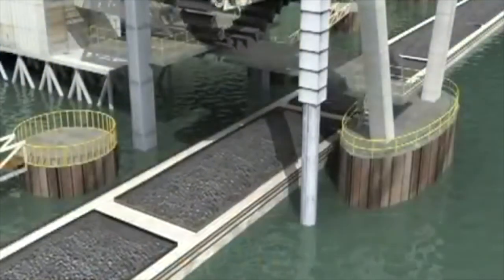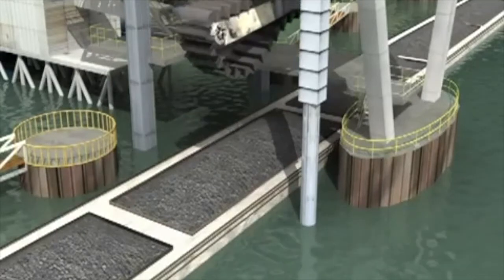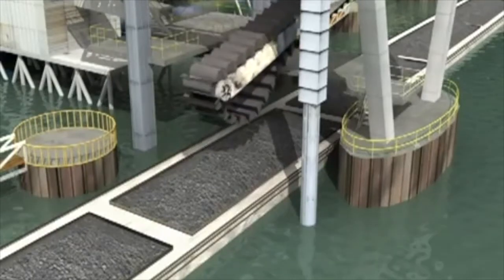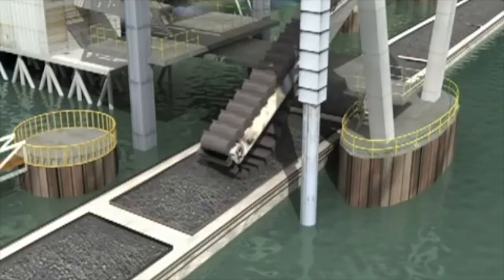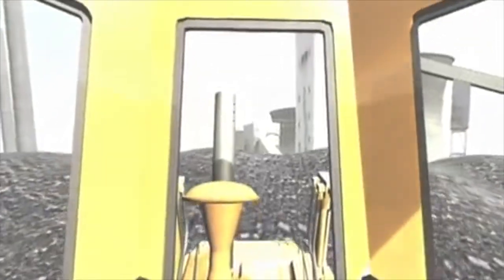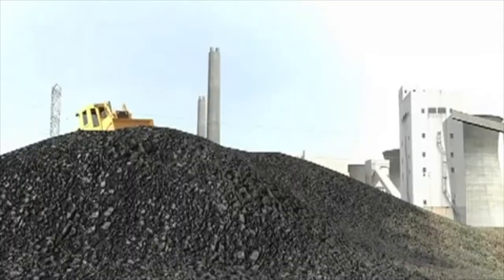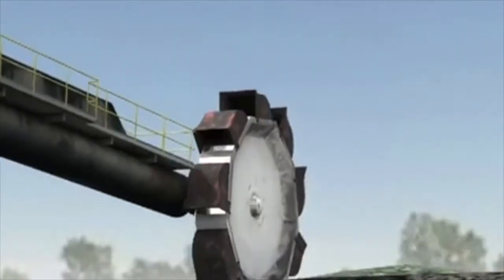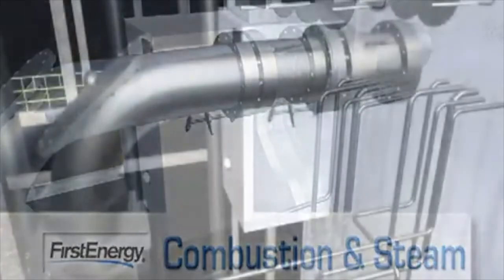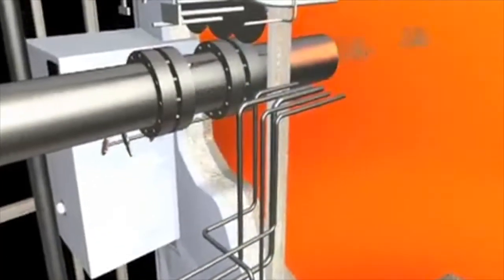Generating electricity requires a fuel source. At this plant, the fuel source is coal, which arrives mainly by a barge but also by rail and truck. Each barge delivers 1,500 tons of coal, enough to keep the plant running for a couple of hours. The plant uses about 21,000 tons of coal each day, so over 1 million tons of coal is stockpiled next to the plant. Large fans add warm air to the powdery coal and blow it into the boiler.